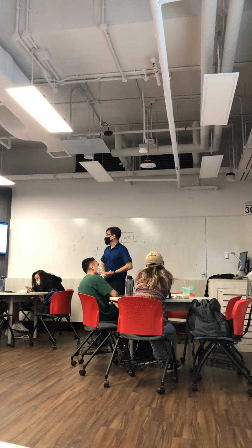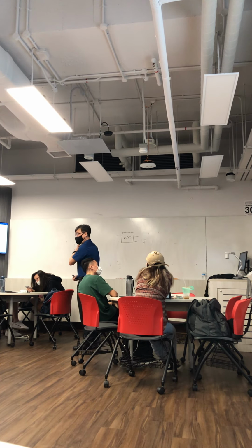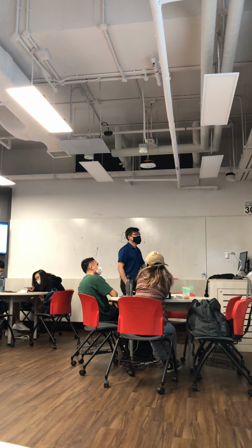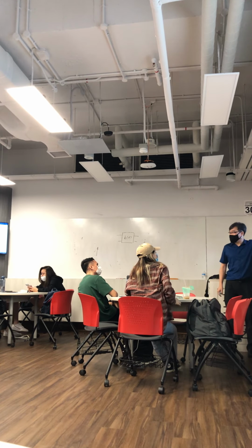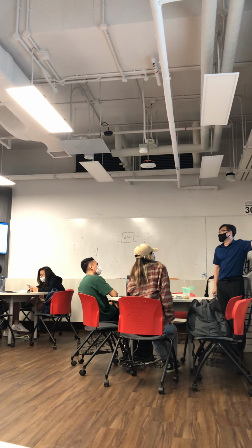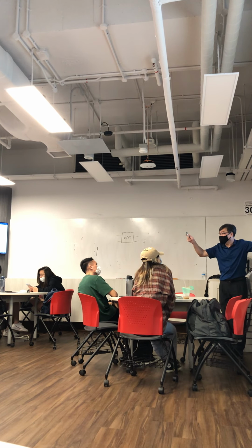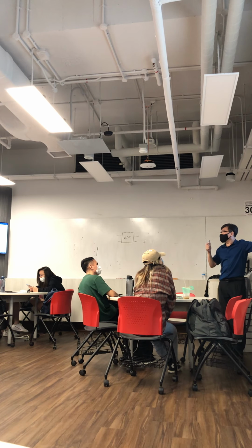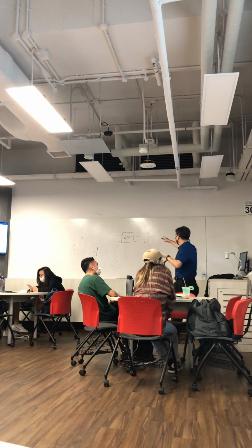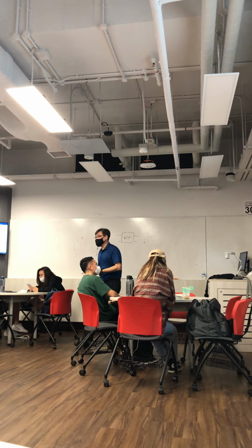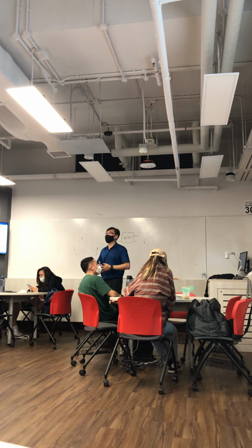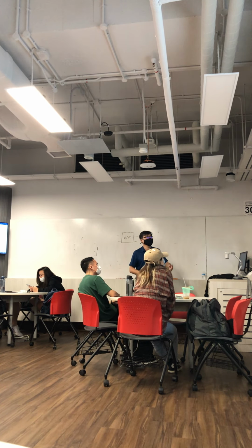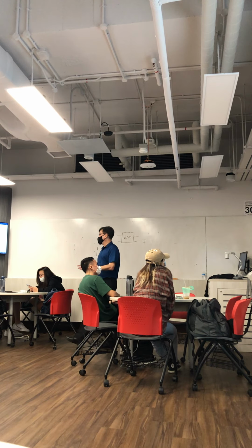The input is converted to a Laplace transform equivalent, then I can predict the output by taking the transfer function H(s). The s appears because you convert from the time domain into the Laplace domain. So this time you don't need to do convolution, just multiplication.